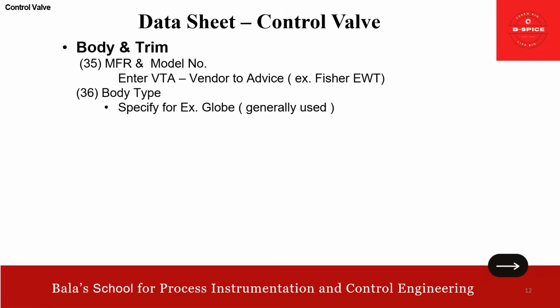Then another type of valve, the butterfly valve. Where do we use the butterfly valve? Always remember, we use the butterfly valve in low pressure drop applications, and of course high flow rate. So if you have a high flow rate requirement and a low pressure drop requirement, you go with a butterfly valve. Of course, it is also used for corrosive services where body lining is required.